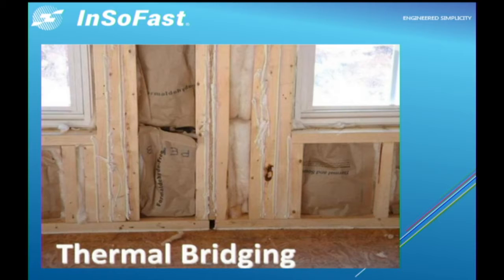So the overall value and insulation performance of that entire wall is really an R-15. So the codes have been written so we can get R-15 continuous, just go with foam insulation or another method to achieve that continuous R-15 code and not have to put wood studs up.